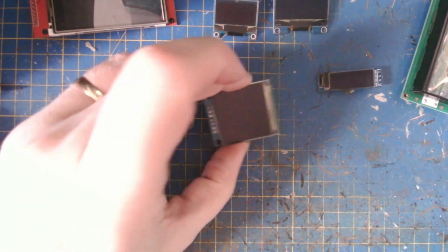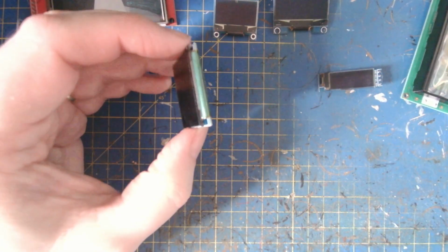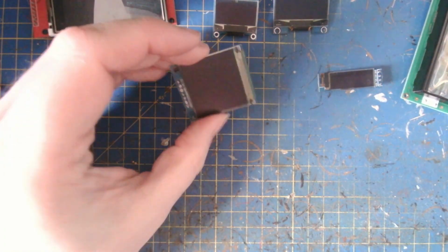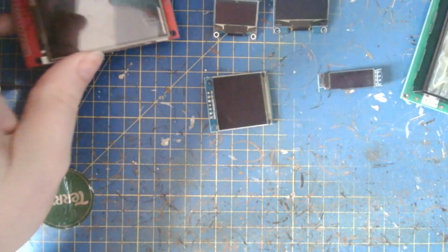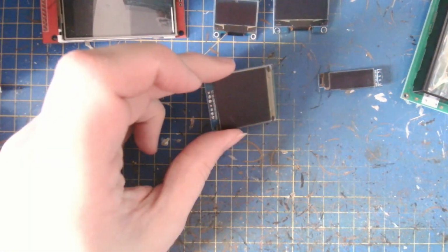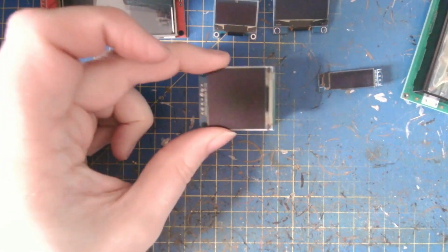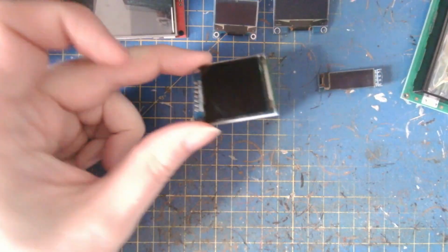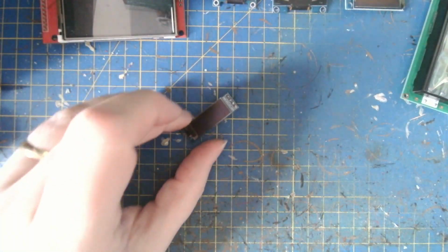So yeah, if you're buying these, have a look at the pinout. If it's got something labelled light, backlight, or LED, yeah, it's one of these. It's a thin film transistor display pretending to be an OLED. Depends what you want and what you're prepared to pay for. But these things are lovely. The colour ones cost quite a bit more. And to be honest, unless you need colour, don't bother.